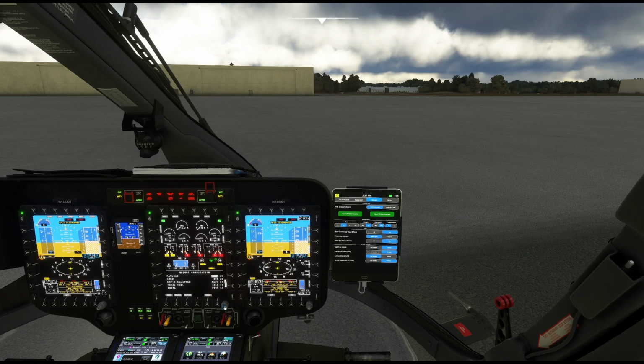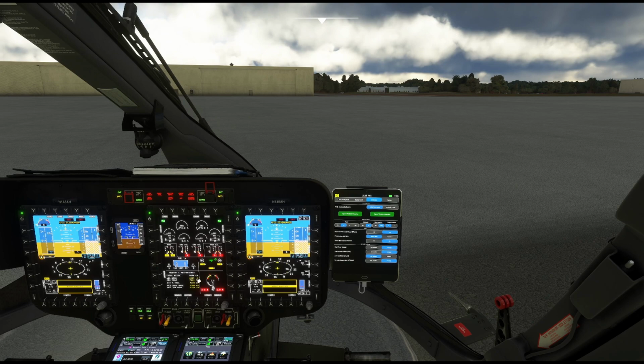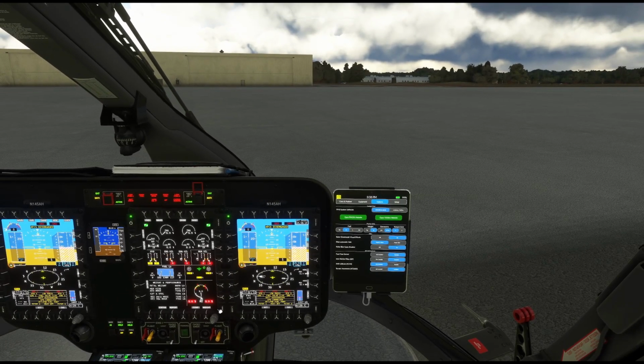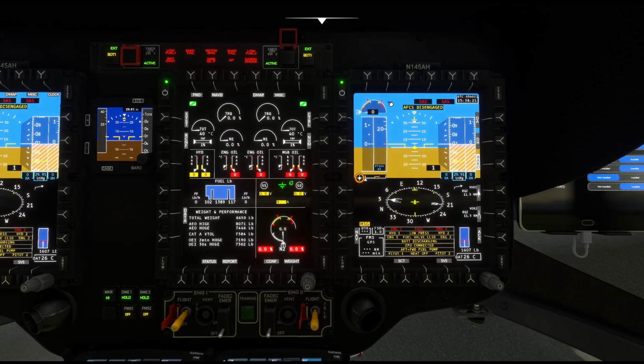If I come back to this and I bring it up a little bit further, now I have exceeded the aircraft total weight. So weight exceeded. It's just saying yellow for hovering out of ground effect. So by that going yellow, that automatically means that I cannot fly. So you would come in here and you would take weight out of the aircraft and validate it, and then come back, and now we are green, green, green, fully legal to fly. All right, so the other thing is you'll notice that this triple tach down here looks a little bit different on this screen than it does up here.